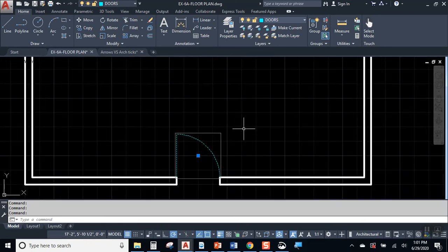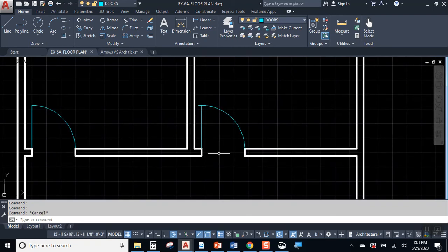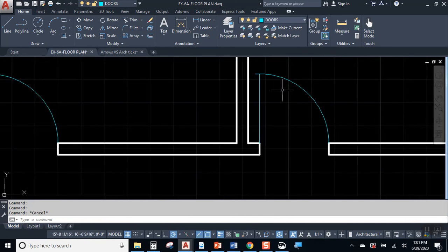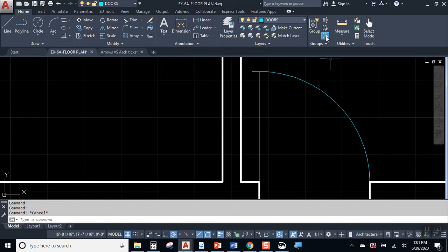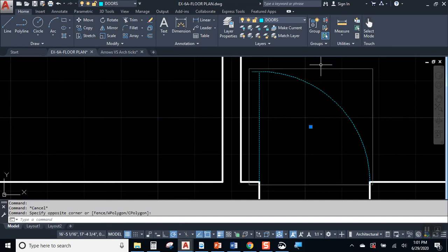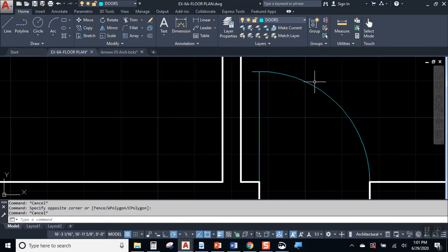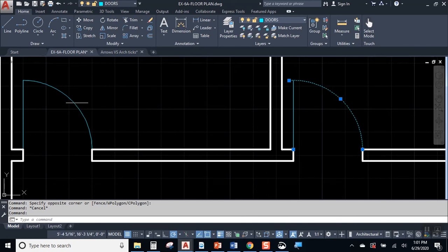See, groups are a simple way of combining a bunch of geometric elements into a single symbol or a single entity, but changing one does not affect any of the others. Okay? So when grouping is on, everyone behaves like a group, and groups are independent. When grouping is off, everything is back to just acting like plain geometry.